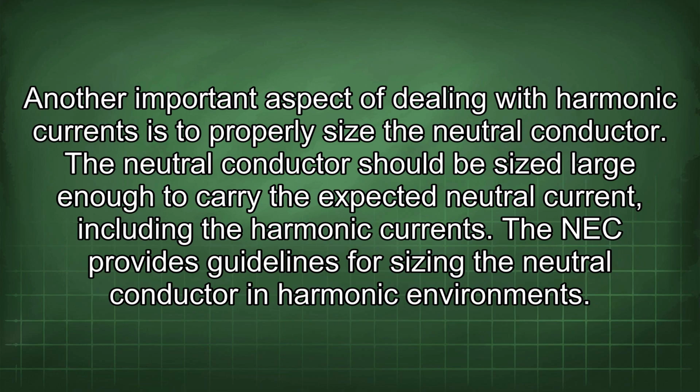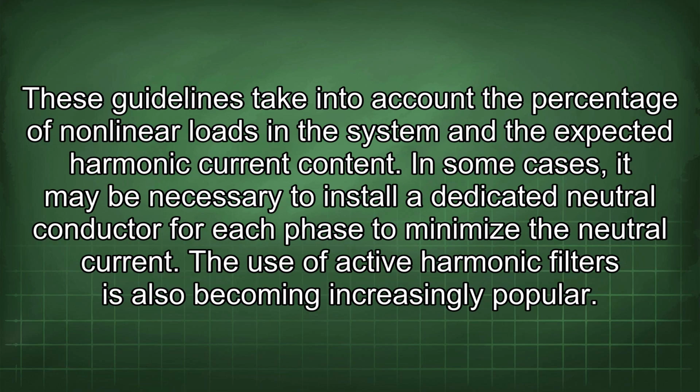Another important aspect of dealing with harmonic currents is to properly size the neutral conductor. The neutral conductor should be sized large enough to carry the expected neutral current, including the harmonic currents. The NEC provides guidelines for sizing the neutral conductor in harmonic environments. These guidelines take into account the percentage of nonlinear loads in the system and the expected harmonic current content. In some cases, it may be necessary to install a dedicated neutral conductor for each phase to minimize the neutral current. The use of active harmonic filters is also becoming increasingly popular.